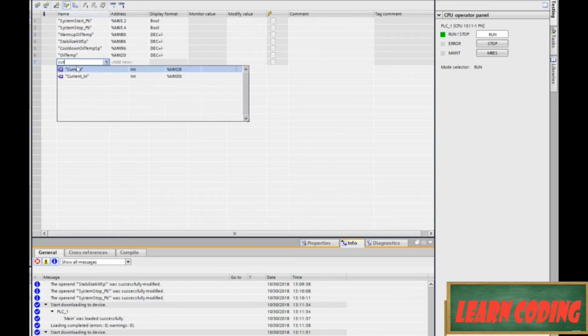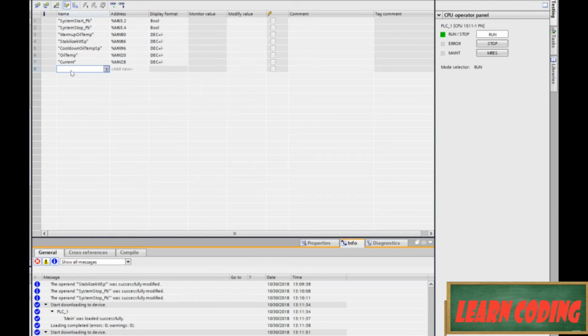And then we're looking for our current. And I don't remember what else we're looking for, so let's just go with that for the time being and see if we can get halfway through this. So our oil temp is 86, and for warm-up oil temp it's going to have to be something above 80. So let's change that 80 right now and make that 100. We'll shoot that in there, so now we know we're not going to bounce immediately.